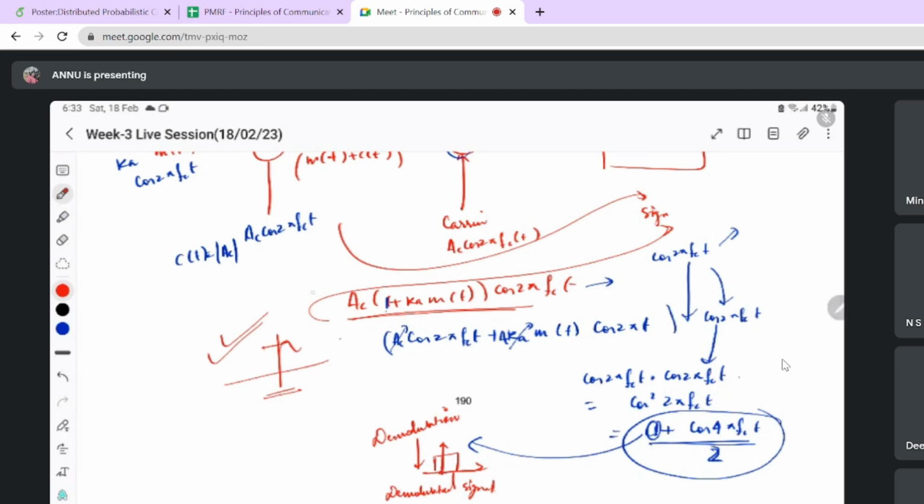Amplitude variation can occur only by adding a signal. So the pure amplitude modulation is actually double sideband, both. Yes, it should be double sideband. That's why we are removing it after. Sir has not done it properly, but there are some methods of getting the DSB-SC modulation from AM modulation, and one of the methods I try to show using that problem which was asked in the GATE exam. So basically, we suppress one sideband to conserve power, right?